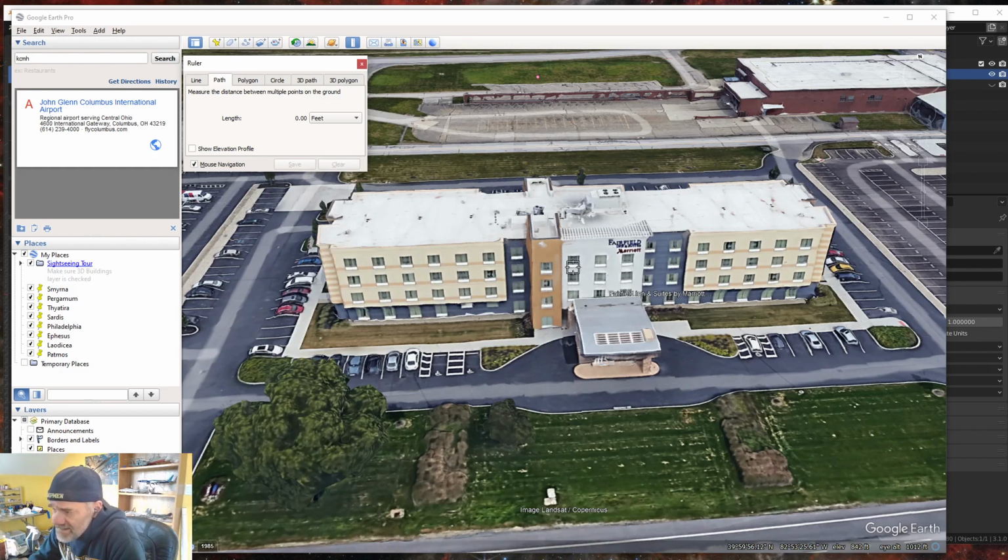All right, so in order to make these work out mathematically, if I have 86 feet, I have 6 windows that are 6 feet, that's 36 feet from the 86. That gives me 50 feet left over. Now, if I count the 5 feet on each side, that gives me 40 feet for these gaps. And I have 5 of these gaps. So that means that they're each 8 feet across. Does that make sense? All right. That's a pretty good guess. It may not be perfect, but it's a pretty good guess.